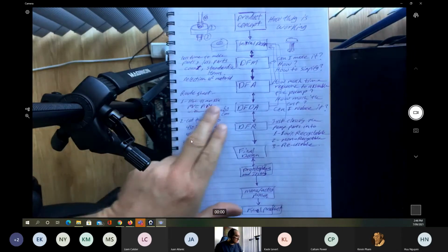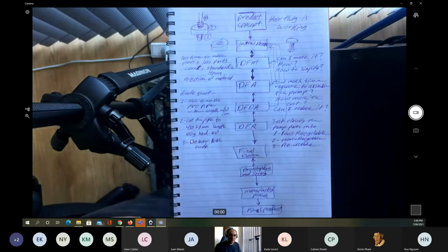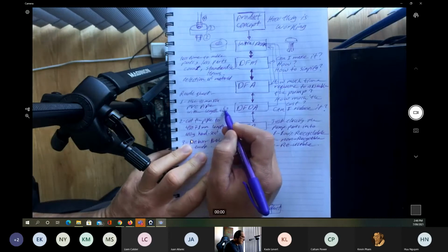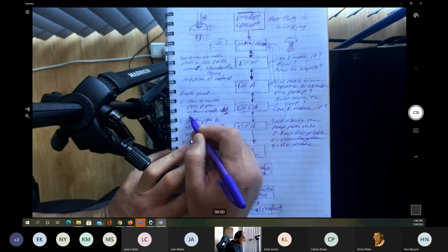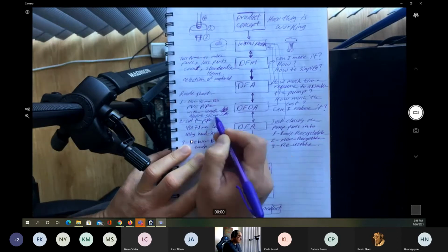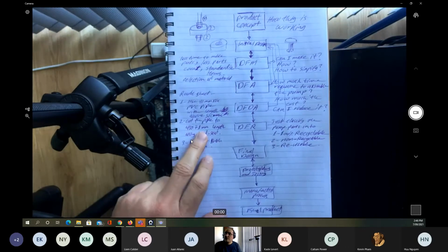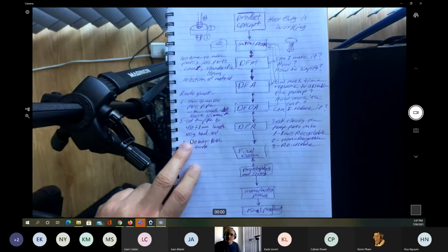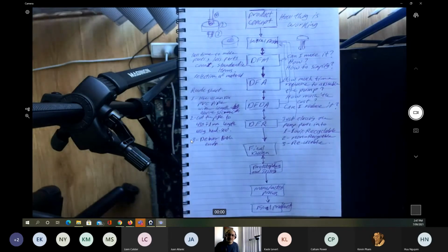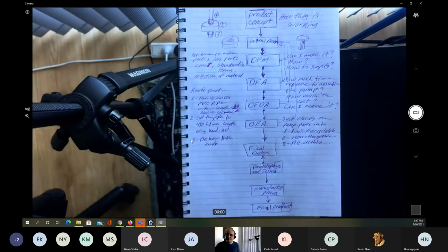So the pipe route sheet: use the 40 millimeter diameter PVC pipe, the initial length of 60 centimeters, just an example, or you don't have to mention that. Anything with length above 50 centimeters or 500 millimeters, and then you are going to cut it down to 450 millimeters. What we are going to cut it with, and what will be the final finishing process, which is to deburr both ends by using the pipe deburring tool. Okay, and that's it. We have the part made.